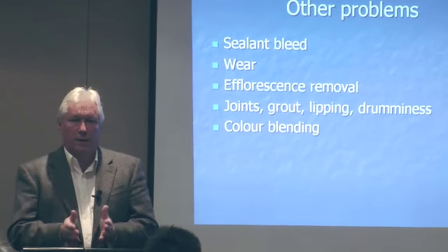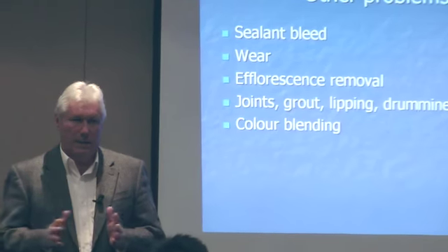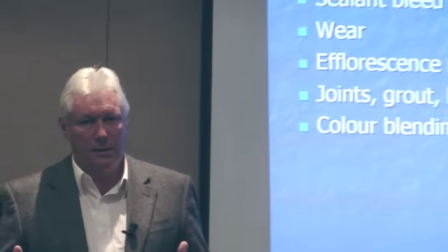The plasticizer is capable of staining in some cases, and so it gets sucked sideways into the edges of the stone. So we can get a wet look down beside the movement joints with the silicones being used. So if you're using these kinds of products, and you have to, then make sure you get one of the no bleed type of products. They're usually described as safe for stone and things like that.